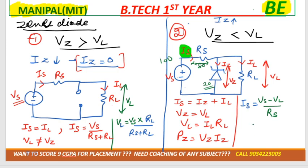Okay, clear? One more thing, sometimes they'll give you the minimum Zener current, maximum Zener current. So whenever they say minimum and maximum condition, in that case we always need to use the second condition. When we do numericals, it will be more clear to you. Okay?